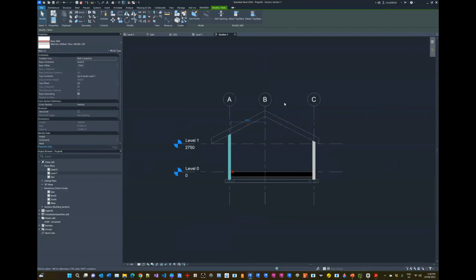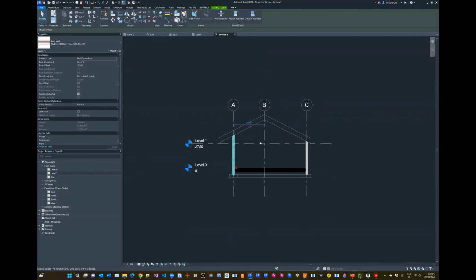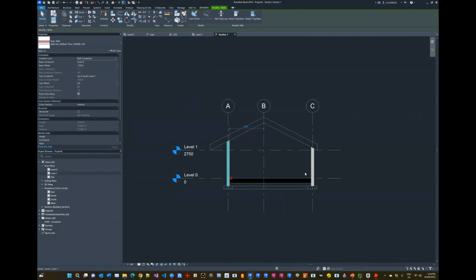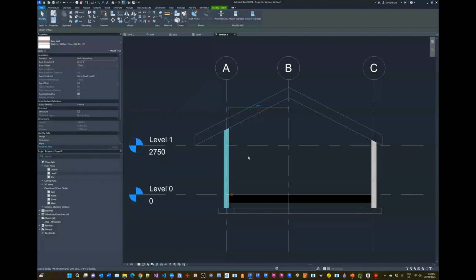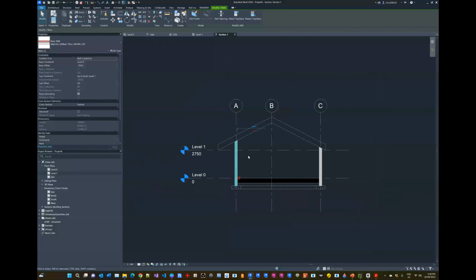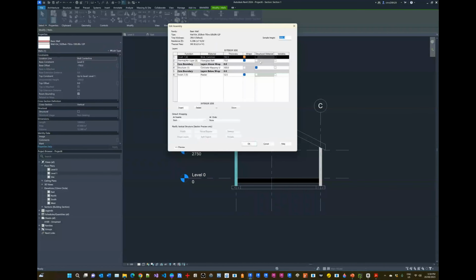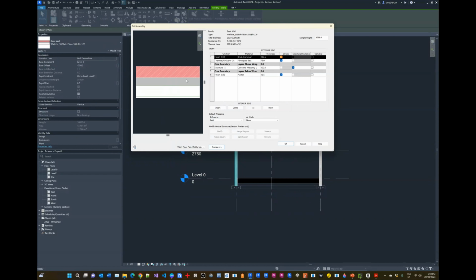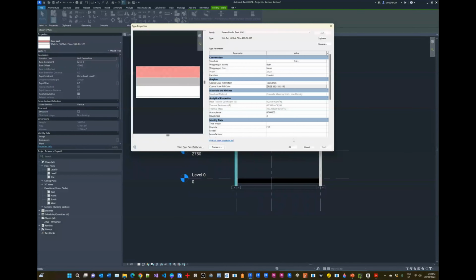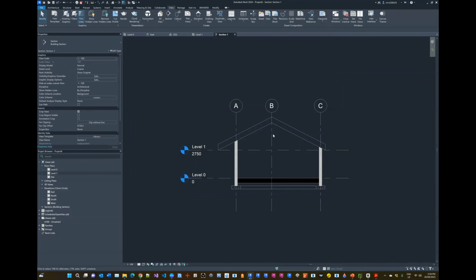It will move in section views, it will move in details, it will move in schedules and quantities that I have produced. It'll update those and recalculate those, meaning that beyond the 3D visual geometrical elements, it's also got information attached to it. So this element is not just volumetric and a dumb entity. It's actually intelligent and it's built up of components that replicate or represent real world elements. So there is intelligence attached to this. And this is really what building information modeling is about.